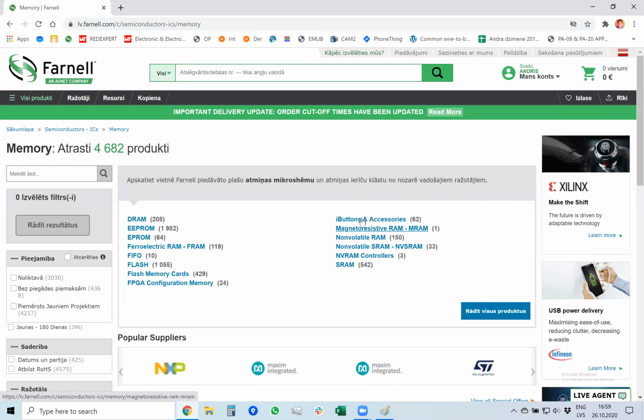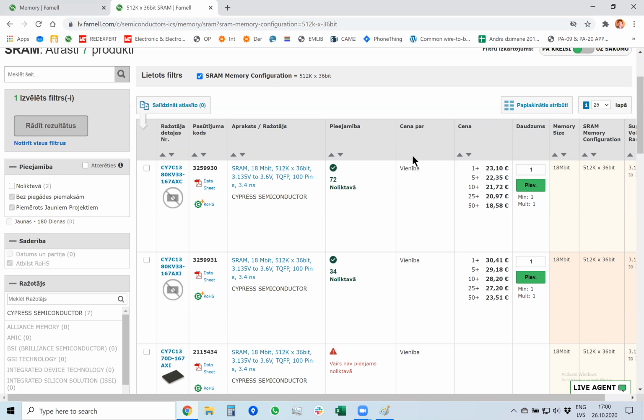So instead of sending just 32 bits from chip to processor, it sends 4 extra bits for error detection. And for example, if it sees that the parity bits are wrong, well, then it knows that some error happened during transmission and it sends the data once more. It just pauses the processor and tries to read the memory again. So pretty smart technologies.